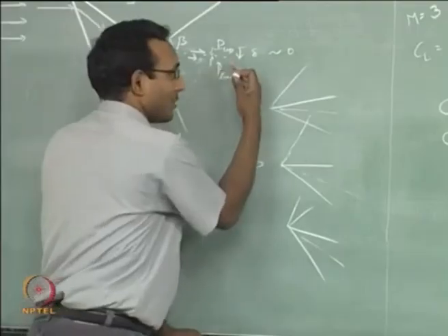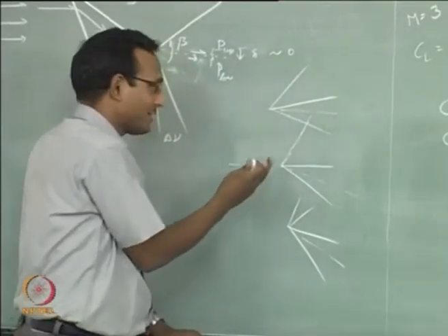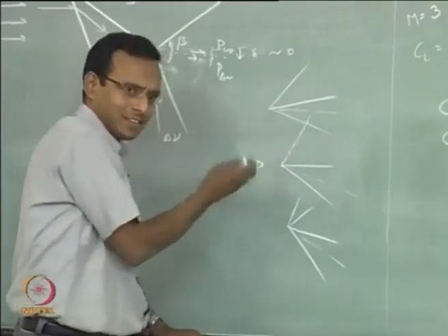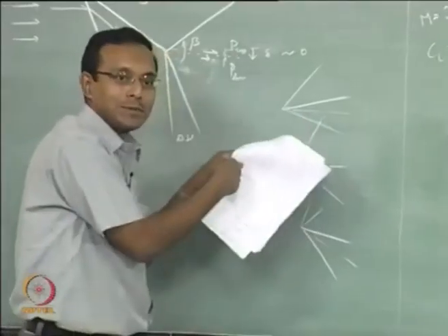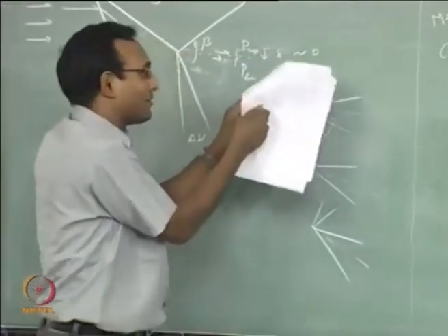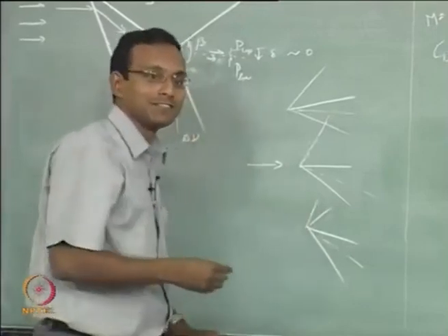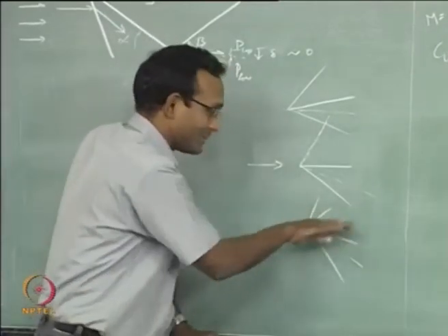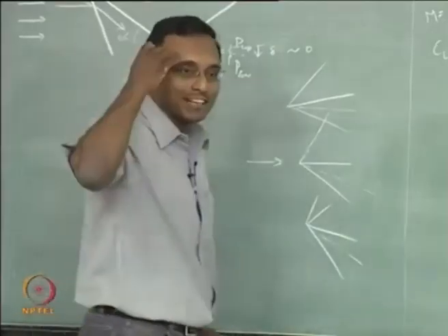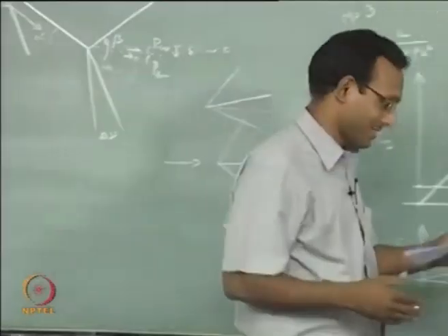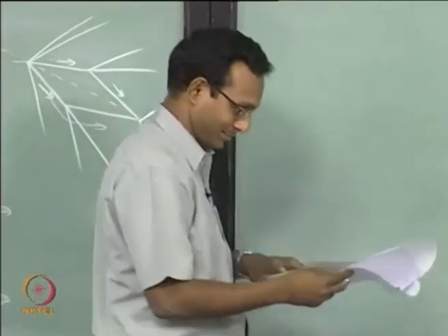The shock slowly becomes a Mach wave, that will be here. After that, that original Mach wave stays, and there will be more and more Mach waves coming out, as if the fan is opening out. You know this Japanese paper fan opens out from one line, that is going to happen here. That is your expansion fan, they call it. So that is going to happen as you increase angle of attack. It is more fun to watch this. You should start feeling these kinds of flows. If you can feel that, then I have done my job teaching you this flow.